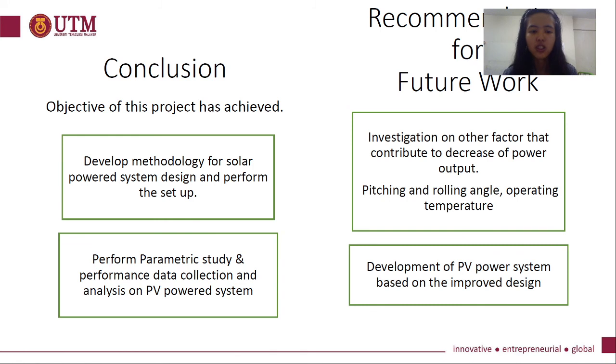I have developed the methodology for the solar power system design and performed the setup, where I used the solar simulator, obtained the irradiance, and did checking, soldering and encapsulation of the PV cells. I also performed a parametric study, performance data correction and analysis on the PV power system, where I did the IV and PV curves, studied the IV characteristics, and predicted the performance of the PV power system.